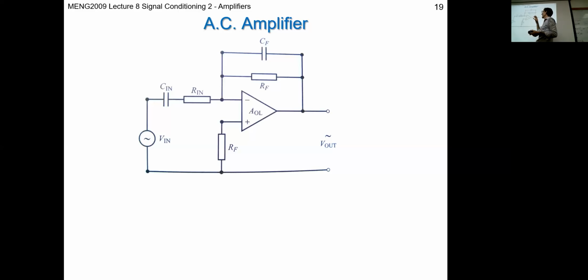So these capacitors effectively create some lag in the system, because as the voltage increases or as your current goes positive, it charges these capacitors, and then when the voltage starts to drop off and goes negative, the capacitors are fully charged and then they start to discharge. So you're introducing a lag. And that's a realistic element in an op-amp or in an amplifier circuit. But it does introduce this kind of phase lag.